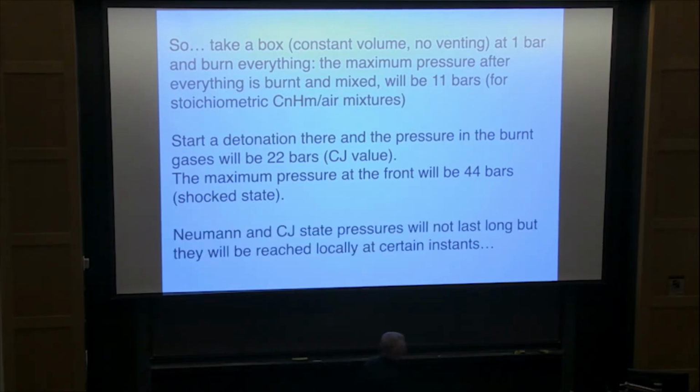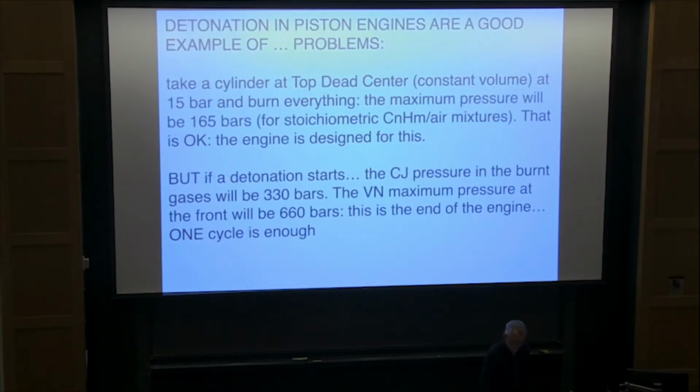Now, even if it doesn't last long, okay, a high pressure is a dangerous animal. Just one example where these things are well known, that's piston engines. In a piston engine, pressures, of course, can be pretty high. And the engine is designed to go to 150 bar, you know, diesel engine even more than that. But consider the top dead center, where you are almost at constant volume, and you start at this moment from 15 bar after compression, which is quite reasonable, and you have a factor of 11, you go to 165 bar, and that's okay. Engine will survive. I mean, it's built for that.